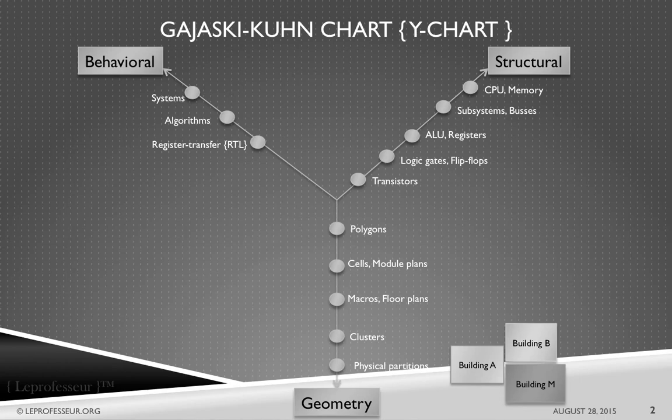Basically, you come up at this level with a design description which has one part that is the memory element, where the values are stored for temporary operations, and then the logic gates, which perform the logical operations which your algorithm defines. So we convert it to a register transfer level description.